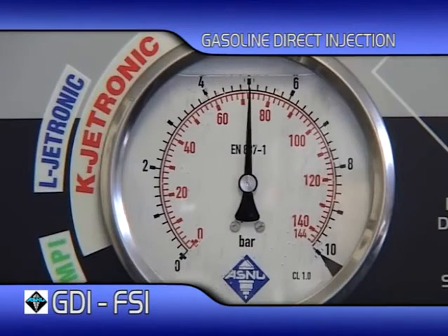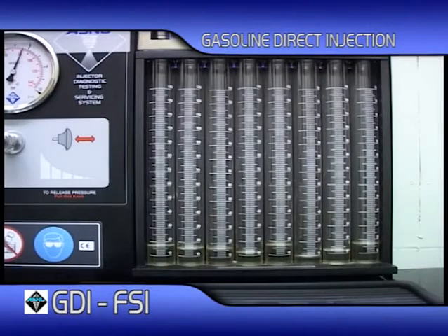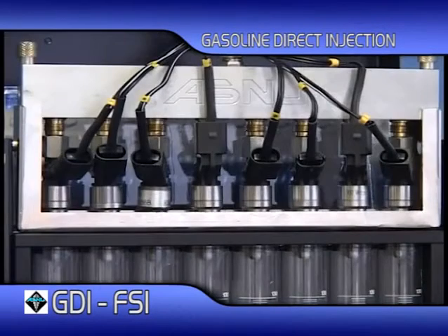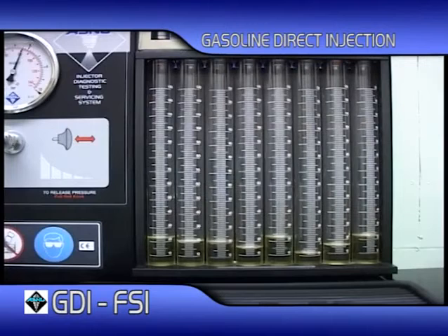The final test is to measure the flow rates. Do not adjust the fuel pressure, it must remain the same. As you can see, if you were trying to examine the spray pattern in the glass tube, you would not see anything or be able to give a correct professional diagnosis of the injector's performance.